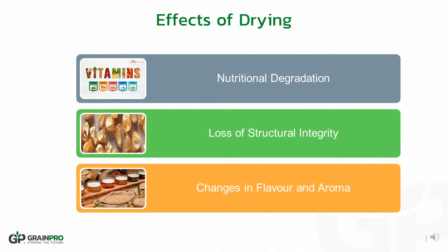Food quality and components are affected by the drying process. Components found in food are those which are sensitive to heat. These include vitamins. When subjected to excessively high temperatures, the beneficial properties of these components are either completely destroyed or substantially reduced. For this reason, it is best to impose limits on the drying temperatures of most food products.